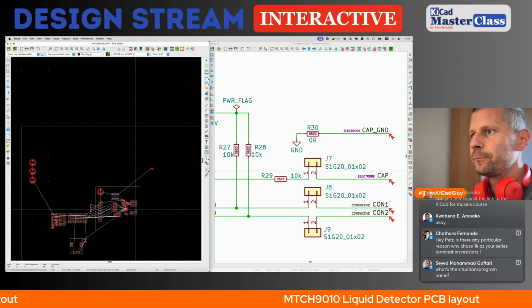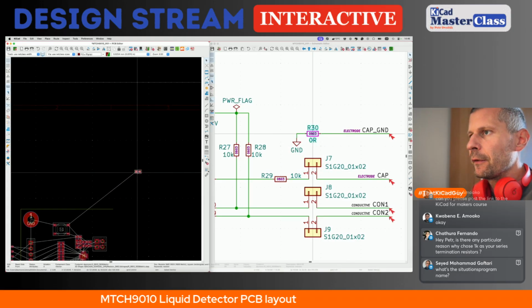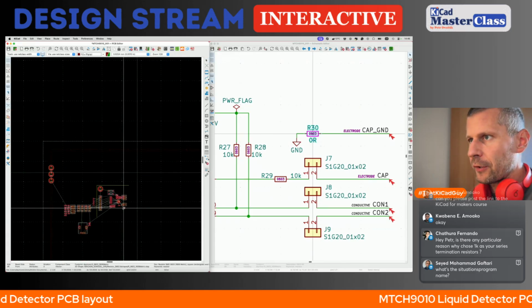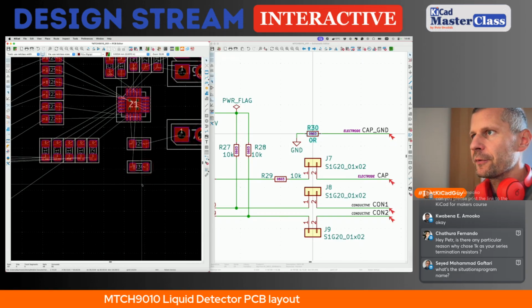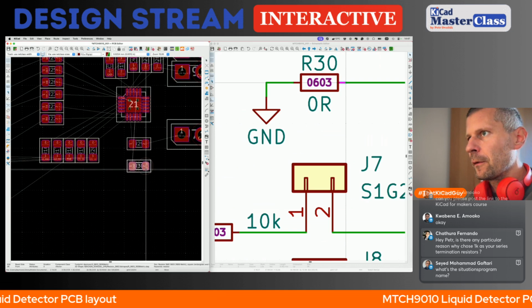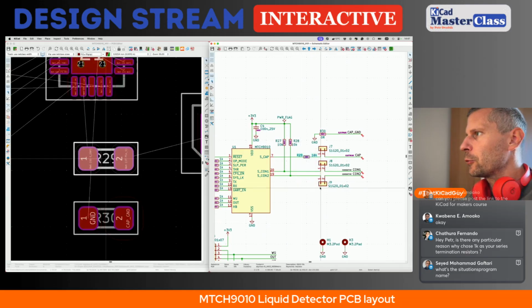So we have the 0 ohm resistor isolating the ground electrode. So we can place it here, for instance, below the serial resistors for the single-ended output.